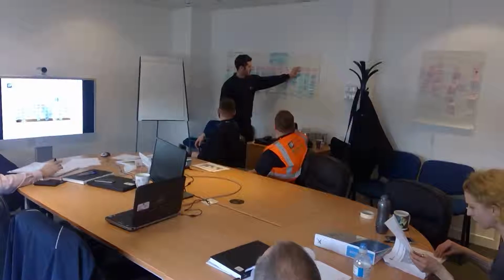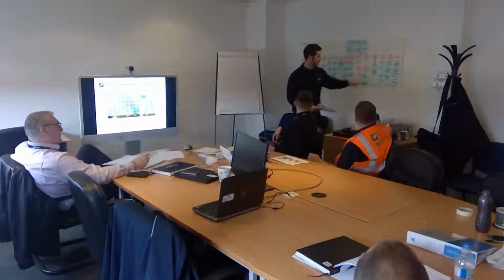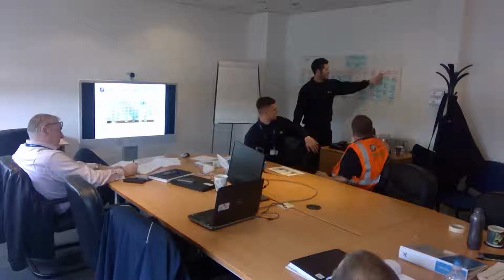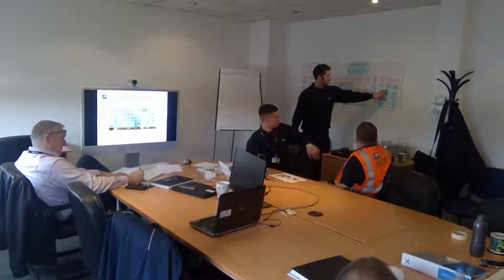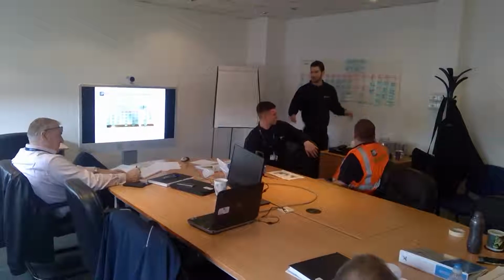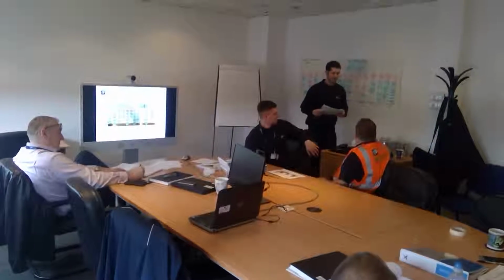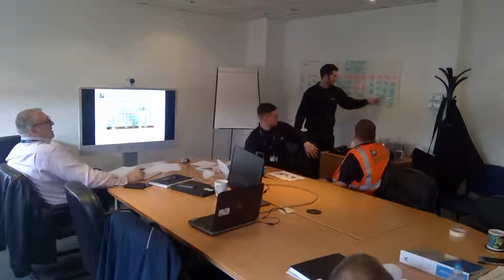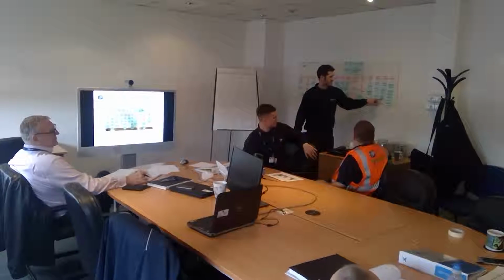Eventually we then get to marking up spool with ID, so permanent marker, wrong ID can go on, it's illegible, joint can be missing from it, so we don't actually know what spool it is. And then we're on to dispatch, which is goods in, goods out department. So missing materials for dispatch, so your bungs, your end caps, stuff like that, they can be missing. Debris can be left in pipe, so when we drill little holes in it for sockets, debris can be left inside it, it's not good. And obviously, part and parcel of that materials, open ends can be left.